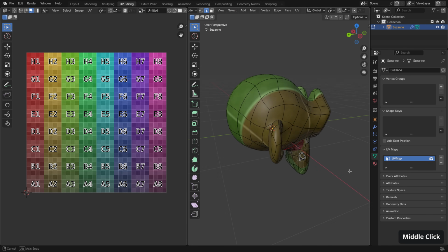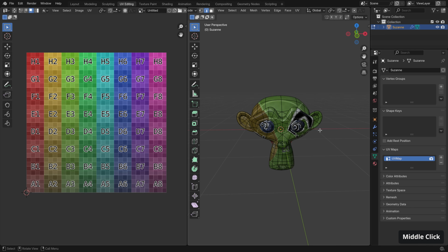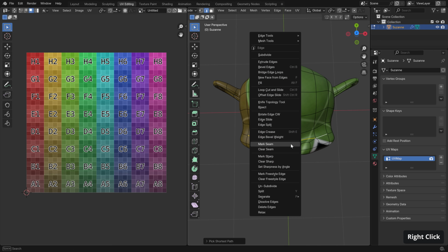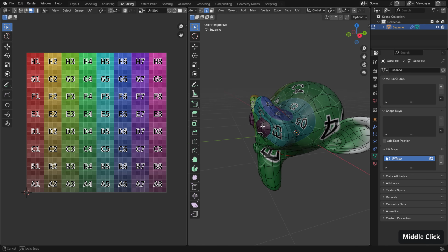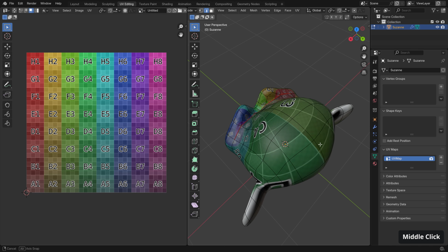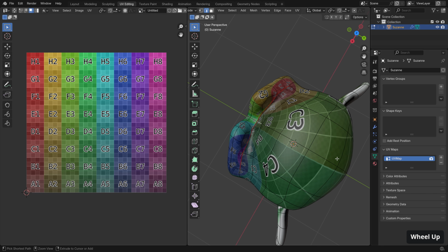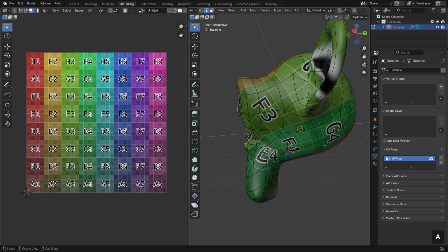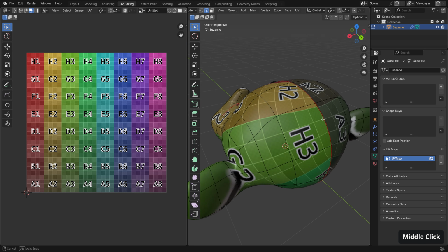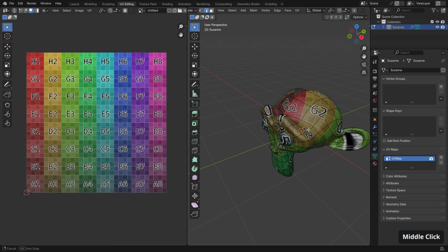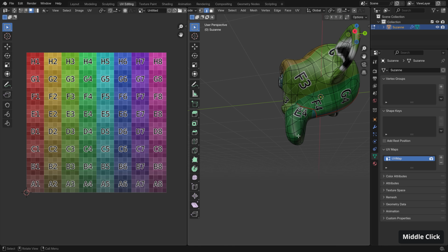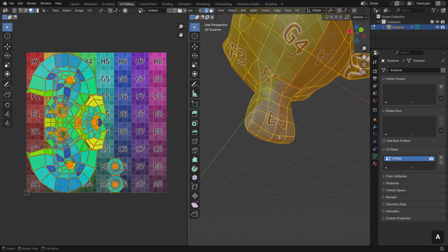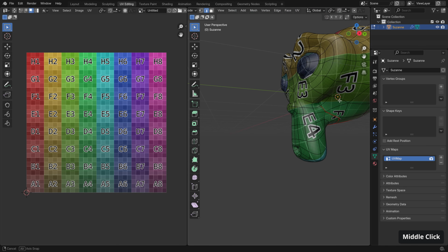Now I want to look if there's any other area that I want to separate out. I'm going to cut out the ears later, but for now I'm going to separate the brow here from the head as well. So I'm going to select this here and mark this as seam as well. Now with those separated out, what I'm going to do now is to cut down the length of this spherical shape for the head. So I'm going to select this here and then cut it all the way across to the other side here. So I'm going to mark this as seam as well. Now by cutting open the head here, we allow it to expand a lot further so I get a better result. Now not done yet, we also want to continue this cut down into the cylindrical shape for the mouth. So all the way to the end here. So let's mark this as seam as well. And as you can see, this now allows this to open up as well.